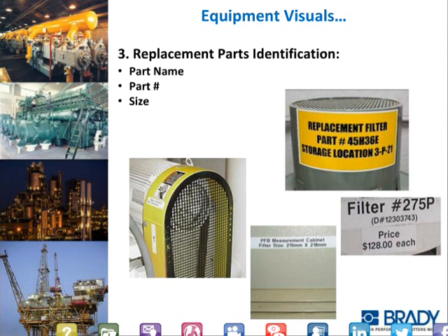Behind that grate is the filter. Well, this label on the outside tells what the filter size is, so you can pre-cut it and have it available. And then one over in the expanded metal mesh over the guard. This team cut the side of the guard off, put the mesh in there, painted it flat black so you can see through it. And the labels on there provide the direction of rotation and the replacement belt numbers.